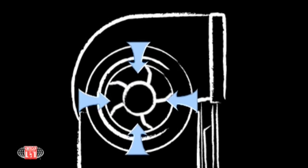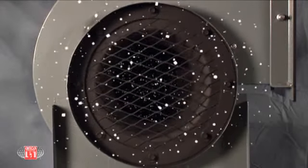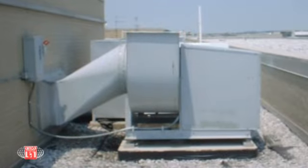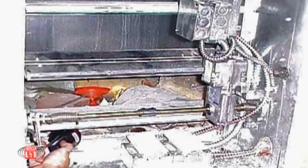The first major impact involves proper fan inlet design. As stated earlier, the airflow at the inlet must be fully developed, symmetrical, and free from swirl. Non-uniform inlet flow is the biggest cause of system loss. Factors adversely affecting inlet flow are insertion of obstructions, elbows and dampers too close to the fan inlet.